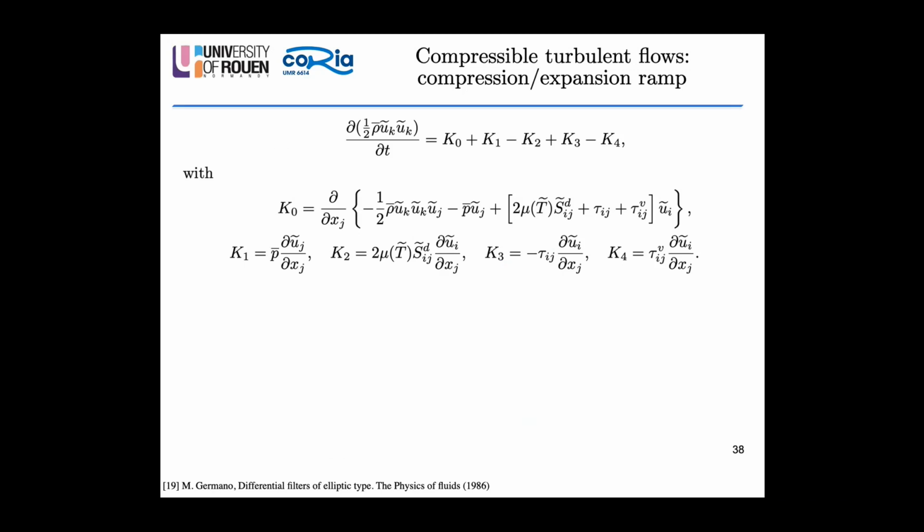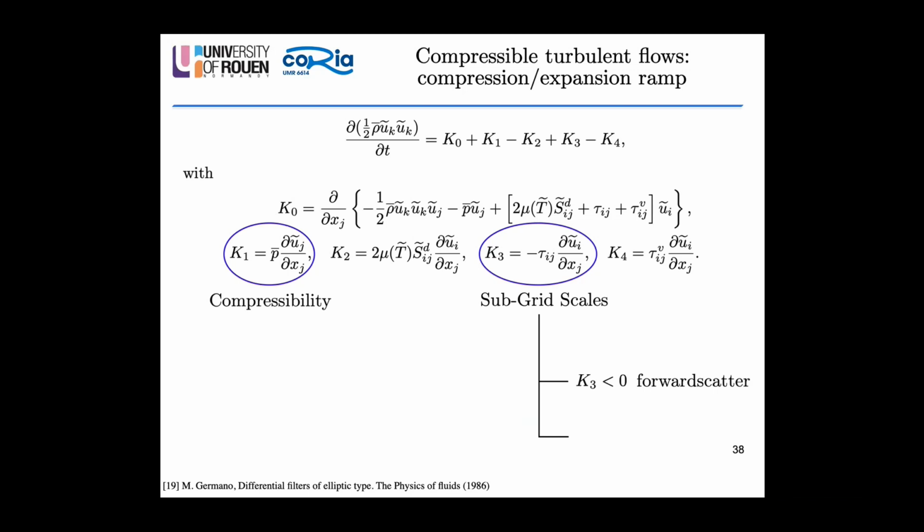compressible conditions. So this is the classical, well, for somebody who works on LES, the classical balance of filtered kinetic energy. And we will focus our attention on the pressure dilatation work, which essentially links the resolved kinetic energy balance and internal energy balance, and the subgrid scale dissipation term, which links resolved and unresolved scales, unresolved kinetic energy. Where if it's less than 0, you have forward scatter, so that the unresolved scales act as a sink of resolved kinetic energy, and vice versa. If it's bigger than 0, you have backscatter events, so that the unresolved scales act as a source